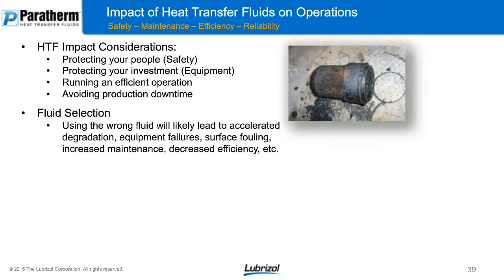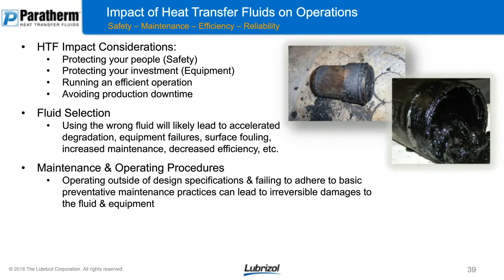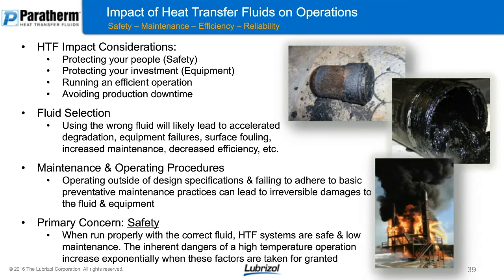Not doing that, you'll get accelerated degradation, improper flow dynamics, equipment failures, fouling on the surface, decreased efficiency, and increased maintenance. If you're operating outside of your design specifications and you're failing to adhere to basic maintenance practices, that's going to lead to irreversible damage of the fluid and the equipment. You could have the highest stability fluid out there, but if you're operating it inefficiently, it will break the fluid down prematurely. And your primary concern, when you run properly with a properly designed system with the correct fluid, this technology is safe and low maintenance. But the inherent dangers of a high temperature operation increase exponentially when these factors are taken for granted.